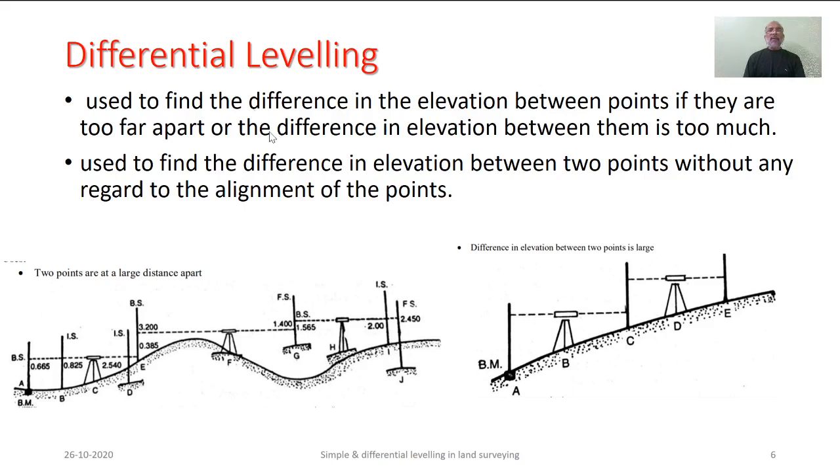Whereas whenever the two points are placed quite a distance apart, or if the elevation difference between these stations is considerable, we have to go for differential leveling. Here, there is no necessity of alignment of the stations between the starting station and the ending station. Our primary aim is to determine the difference in reduced levels of the stations under consideration.